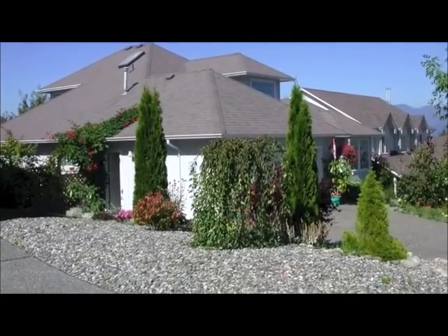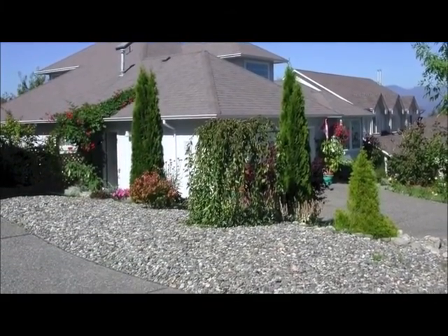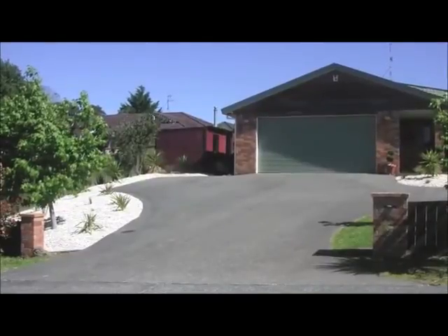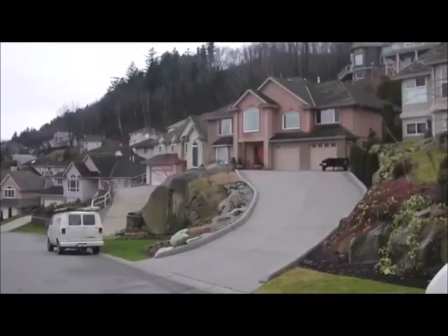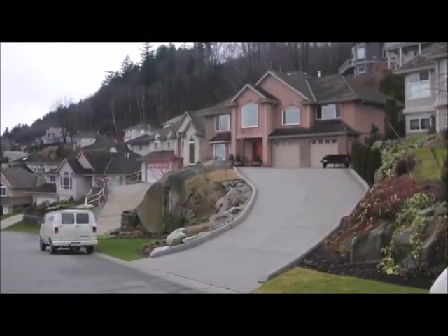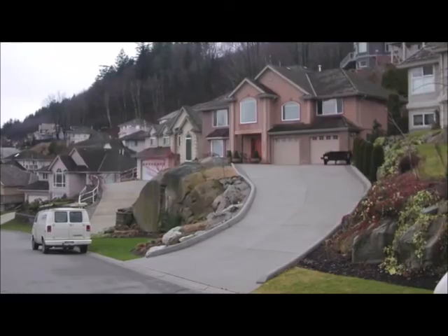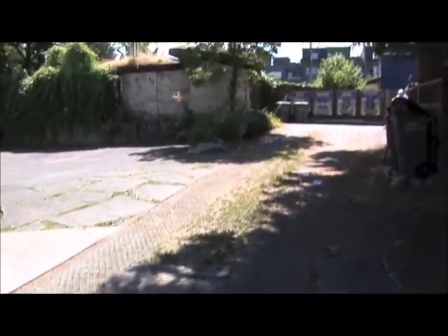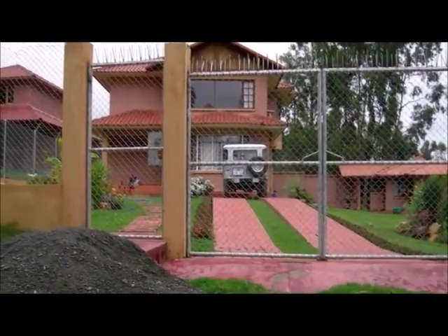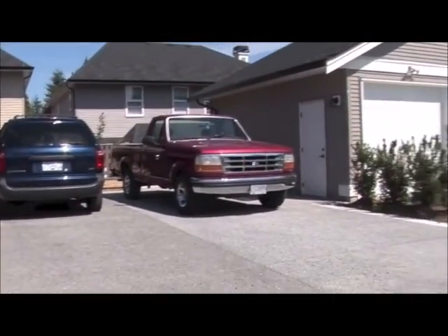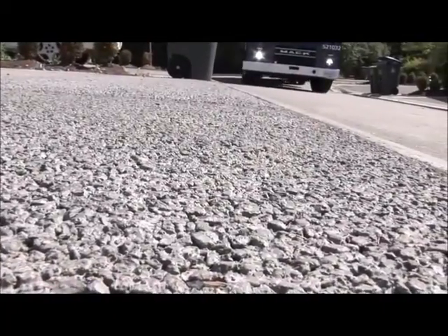As we saw on Bowen Island, driveways are a great opportunity for homeowners to reduce impervious surfaces on their property. Conventionally, driveways are paved using concrete or asphalt. All rainfall that lands on them becomes runoff. Using an alternative driveway design can allow water and contaminants to infiltrate into the soil. This can be done using pavers and grass, a ribbon driveway, or pervious pavement that directly absorbs water. These options are effective ways to reduce the stormwater runoff generated.